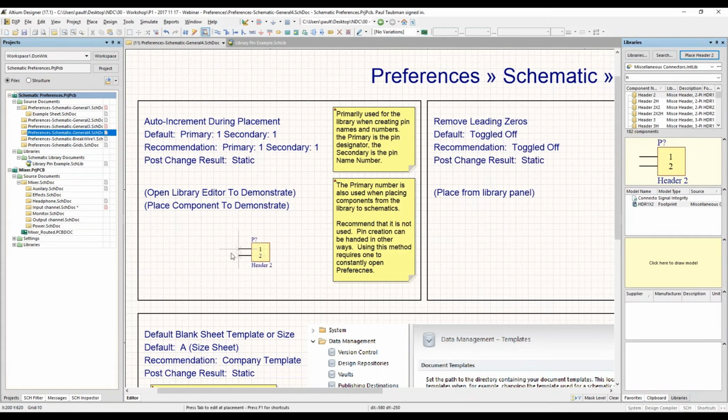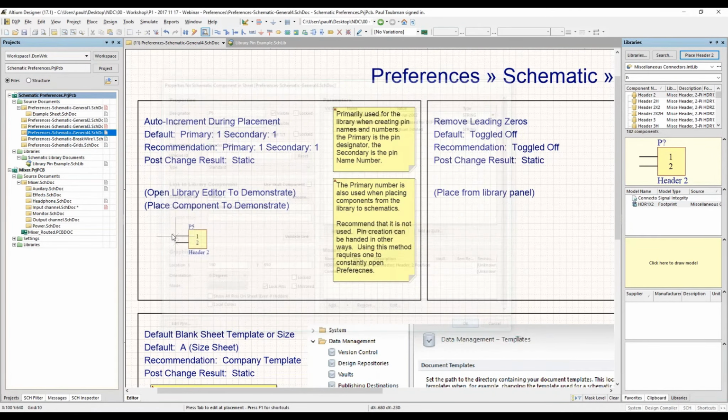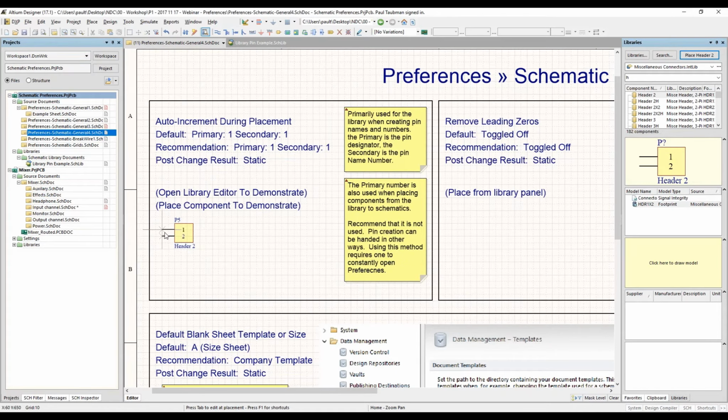And I'm going to place down a couple of parts. So what happens is that when I go in here, I still have to seed it. But let's say I'm going to start it with 5, and I want to increment 5 every step thereafter. Well, the preferences allow me to do that because I've set this now to 5. Okay? And that's what I can do with that over here. So make sure you set the first one correctly, because it's always going to base it plus whatever your initial one is. So if I started with P1 and my preferences show 5, well, the next one's going to be 6, 11. You get the gist at that point, and it's not what I'm going to want to have.